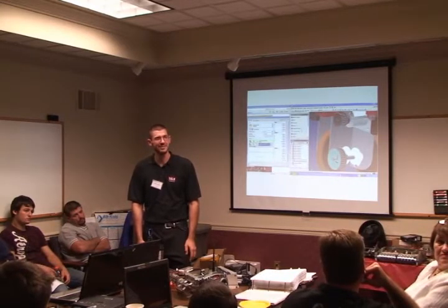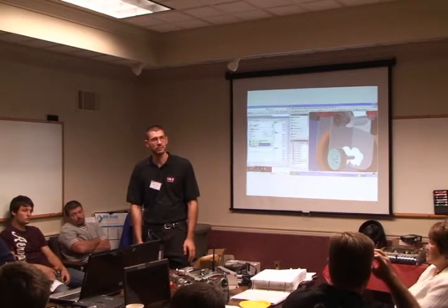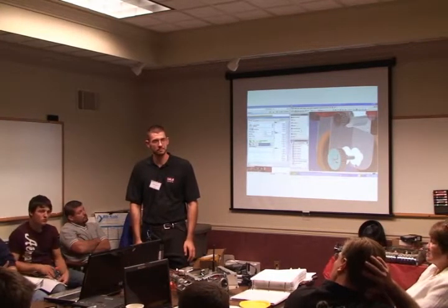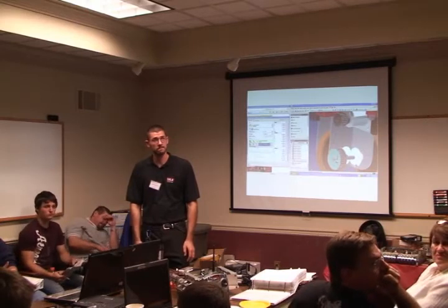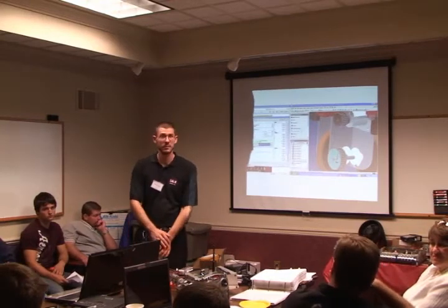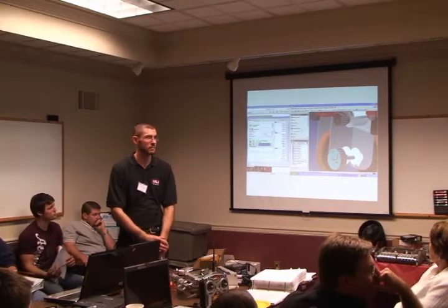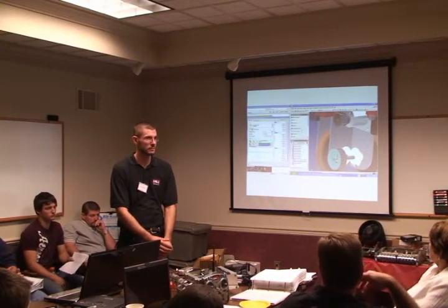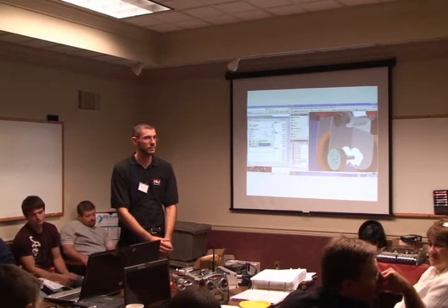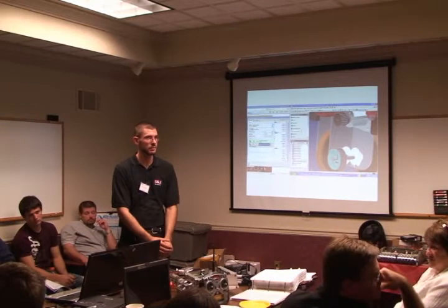And your drive belts center to center, if you choose a 4-wheel drive design, that should be at the top of your list on your prototype, to get that so that you don't have to go through tensioners. We've had to use tensioners already, and the tensioners add weight. You don't want to put weight into things that aren't going to be helping your weapon. That right there is probably one of the most important aspects of the drive system: center to center distance. And there are online calculators, like if you go to Stock Drive Products, they've got a calculator there for you to say you've got this much distance between your centers, and here's the diameter of your 2 pulleys. What belt do you need?